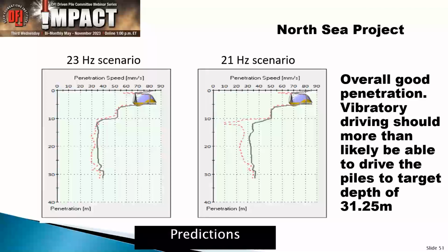A participant asked, can pre-drill or relief drilling be used for early refusal situations? And how will pile capacity be affected because of that pre-drill or relief drilling? Well, it depends on what kind of pile you have, but if you pre-drill through a load-bearing layer, then you need to find something else underneath there that has a load-bearing layer. But in and of itself, most of the time, pre-drilling is no problem.